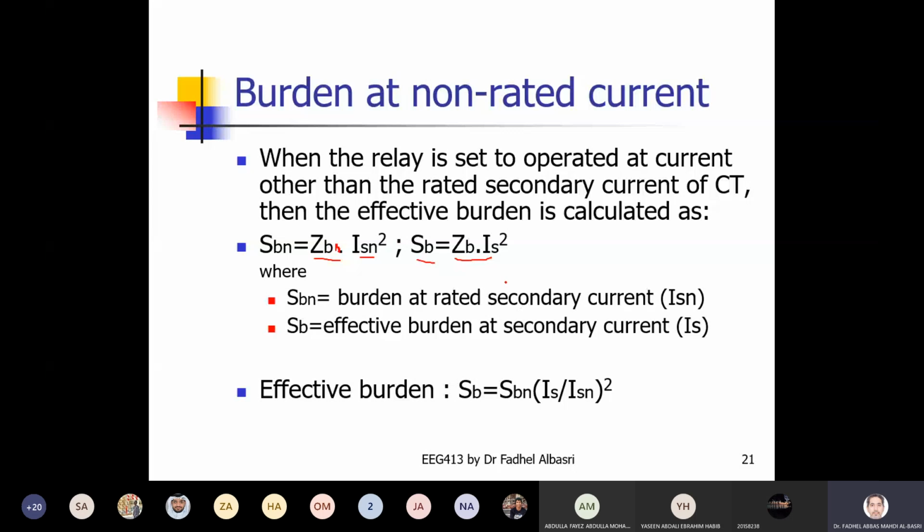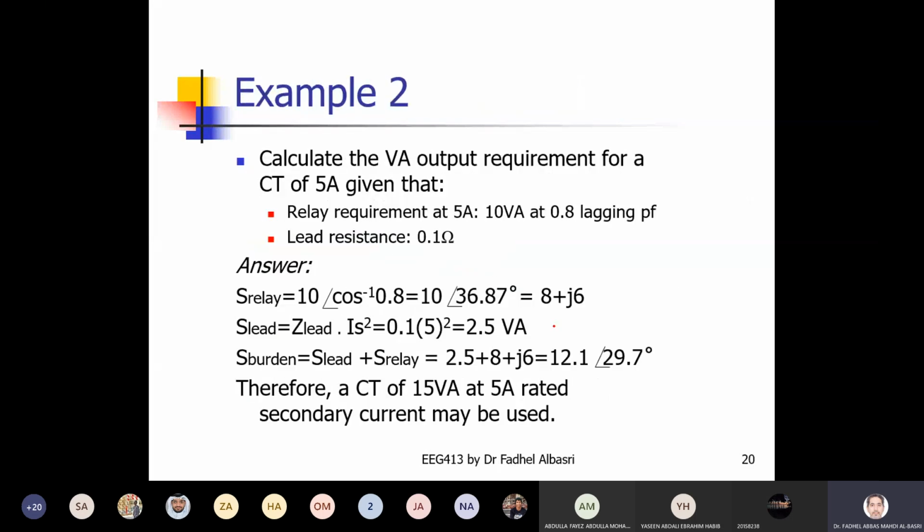So this is one condition that I have satisfied today: that we should choose a CT burden suitable to the load that will be connected to it. Otherwise, it will be overloaded. And overloading means overheating of its winding.